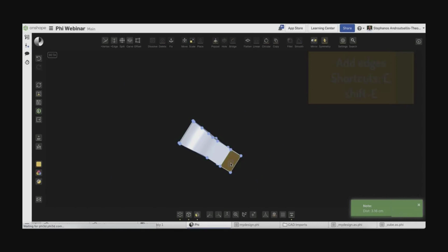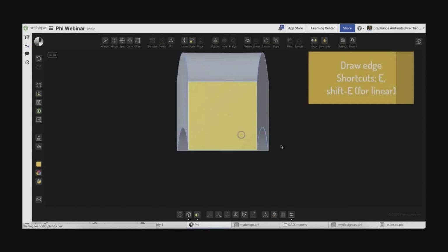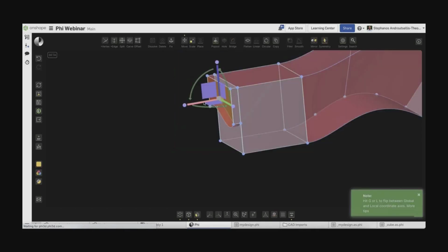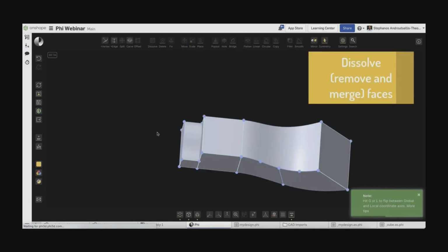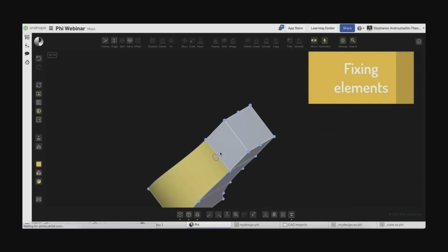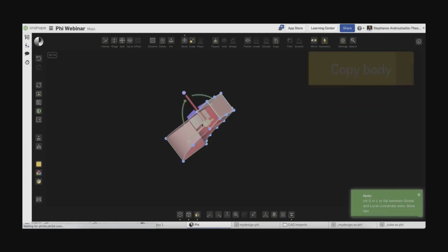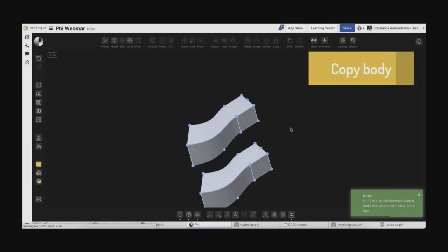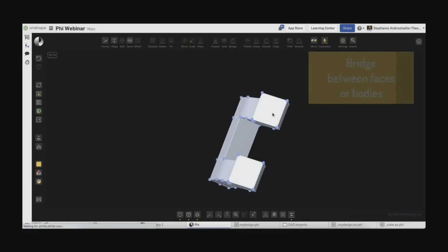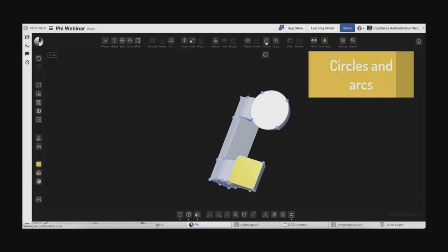And any edge you add, like you saw there, or even by directly drawing it on a face with your mouse, as you see here. So this new edge is completely valid and available for you to use in your design. So here we popped out a new surface. And you can also eliminate volumes, delete parts of your body, of course. Or as I mentioned, you can make copies. So we switched into a two-body environment, which we then quickly reconnected with a bridge into one.